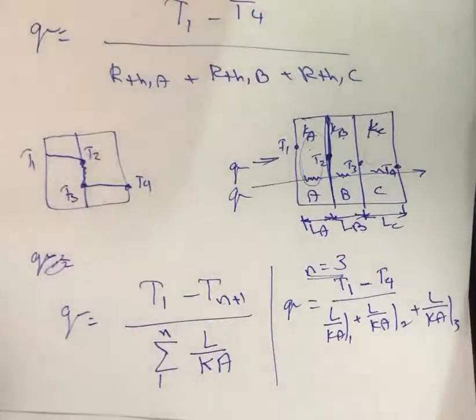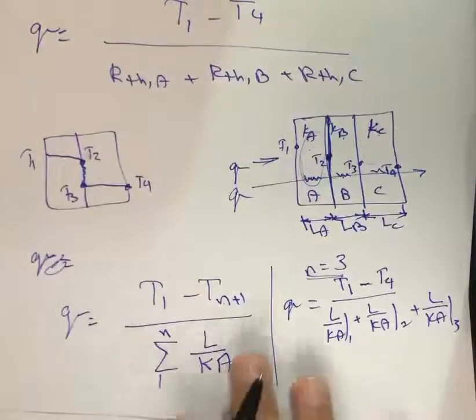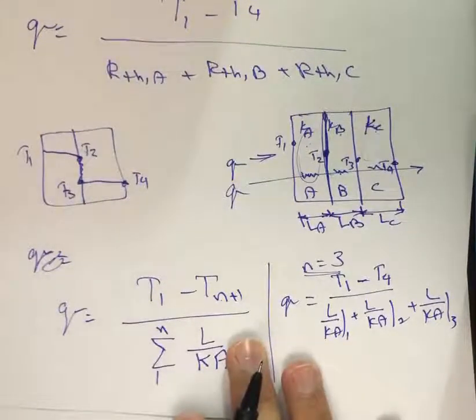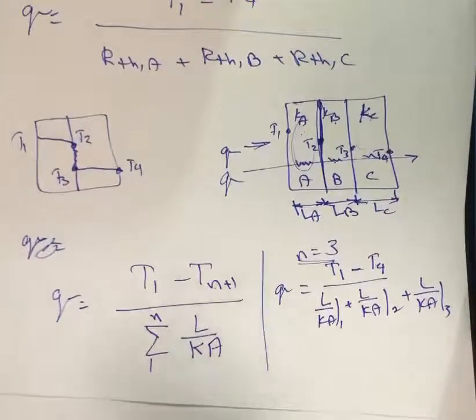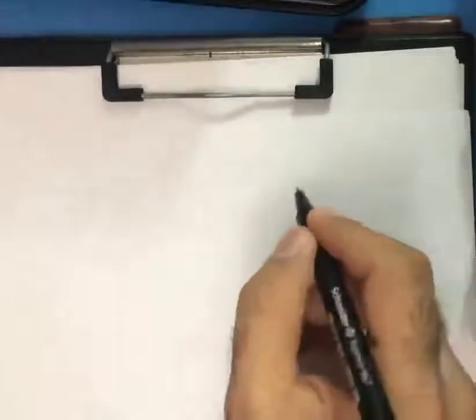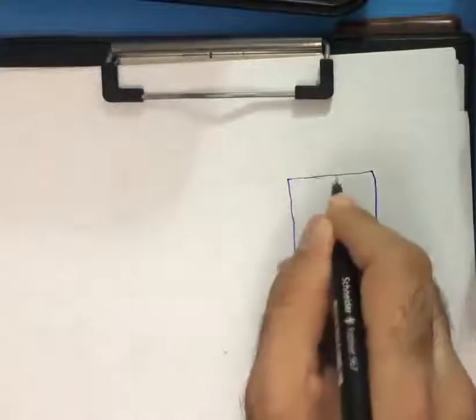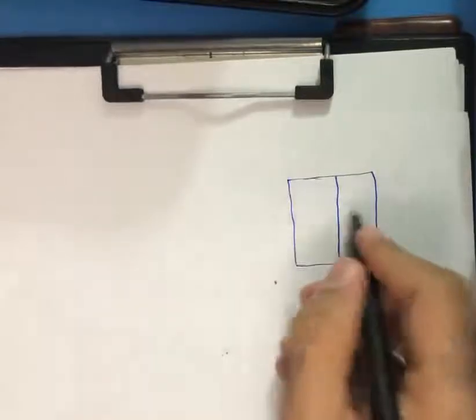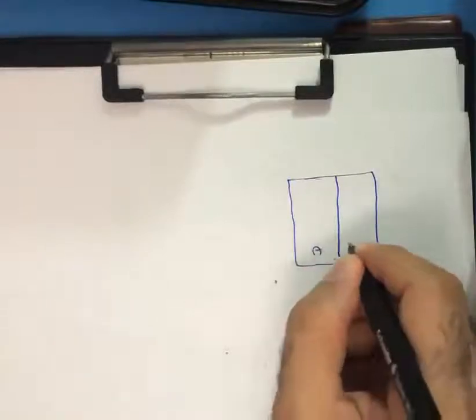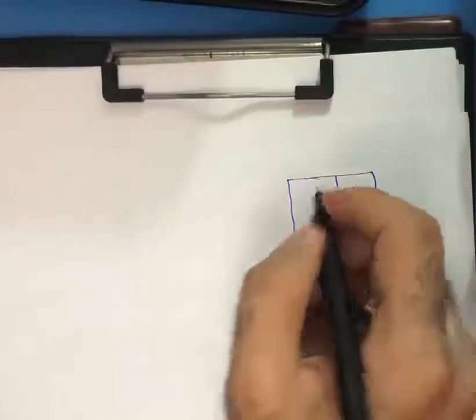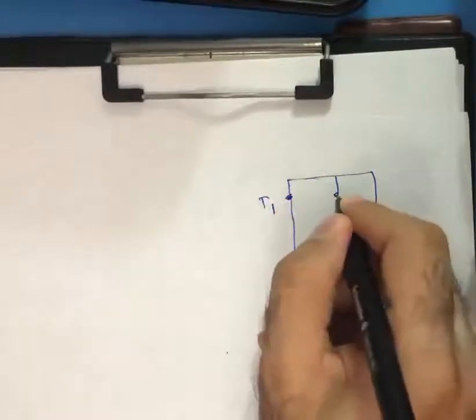Now, after we complete this type of heat transfer, let us treat another case study, which is if we have a thermal contact resistance in a plane wall. It will actually not be very different, because all we have to do is add this thermal resistance. So if I have, for example, this composite wall of two walls, wall A and wall B, and let us write that this is T1, this is T2.